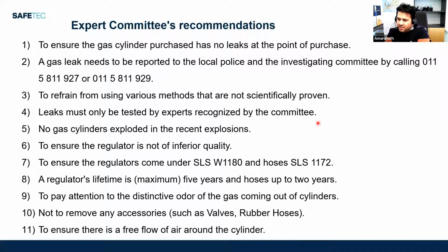guidelines for the companies when they change the compositions and other sensitive parameters. So in my understanding, we need to have very strict regulations for the suppliers when it comes to the gas composition and also the percentage of mercaptan, ethyl mercaptans, that we use to identify gas releases. Those recommendations I couldn't find actually. Maybe they are introduced in the government regulations, but they were not in the expert committee report at least.